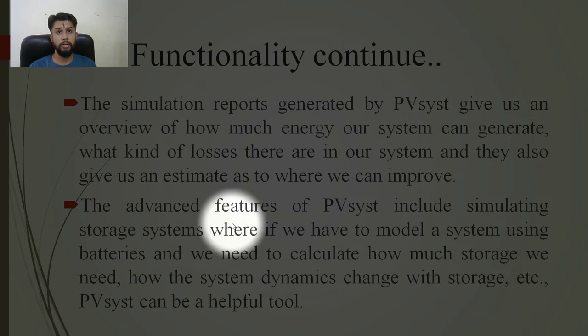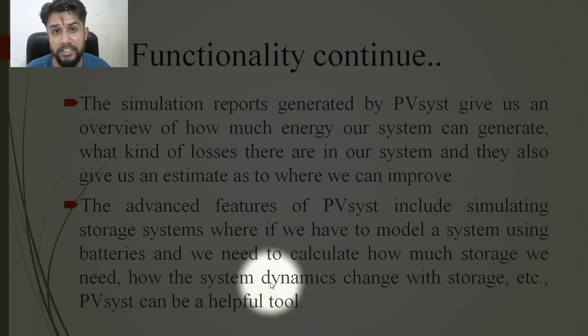For this, we require the consumption limit of that consumer, as well as how much storage capacity we require, considering the days of autonomy, power failure, etc. This dynamic design we can easily carry out with the help of this PVsyst tool. So with this tool, we can design on-grid, off-grid, and hybrid systems.